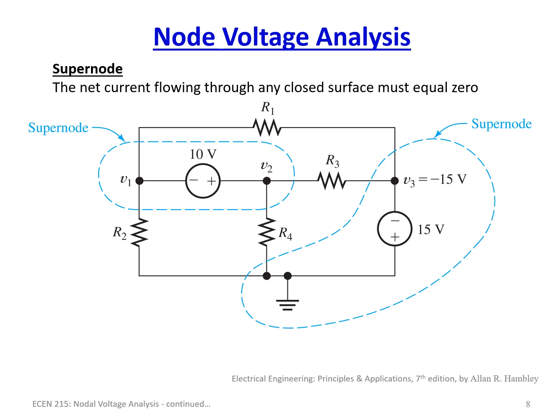But all supernodes is talking about here is we can combine everything up and create one set of master equations. Obviously here we've got these two power supplies, this 15 volt here and this 10 volt here, which using nodal voltage methods complicates the math a little bit, because as you just saw in the example we just had, we had to create this I-15 volts, this separate term.